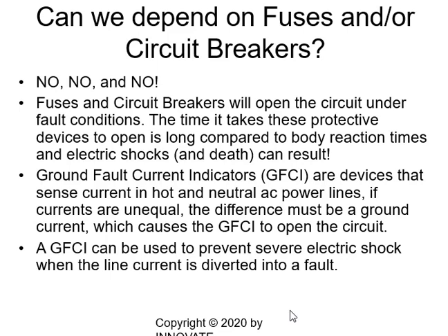So the time for the body reaction is much faster than the time needed to generate a fault, to trip the circuit breaker, or to break the fuse. The time that the current will flow through your body is faster, and this may cause huge damage and even death. So you cannot rely on fuses and circuit breakers at all.